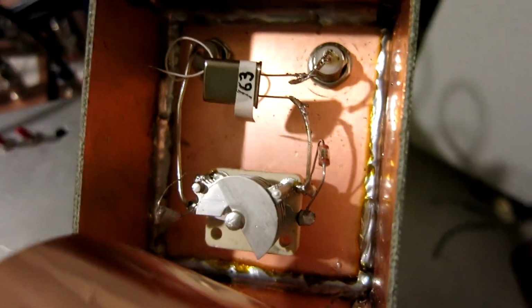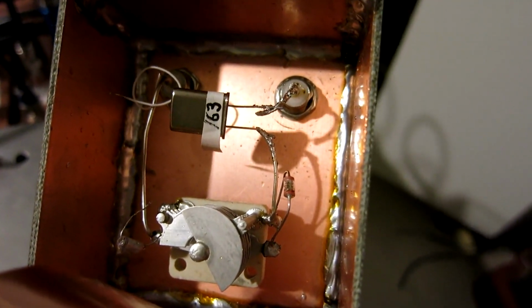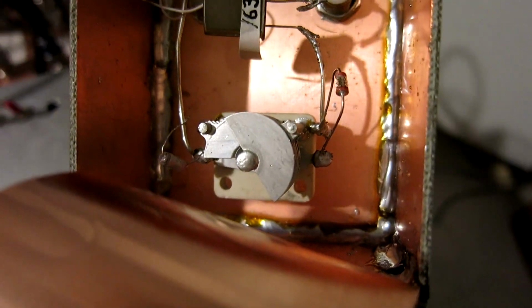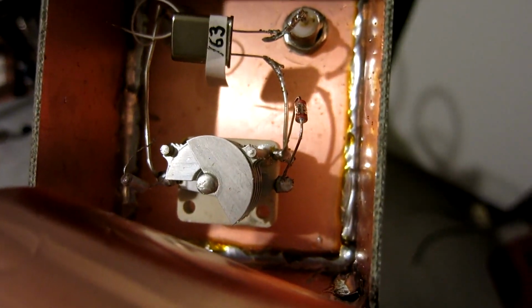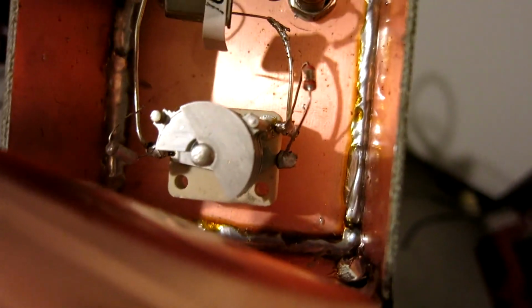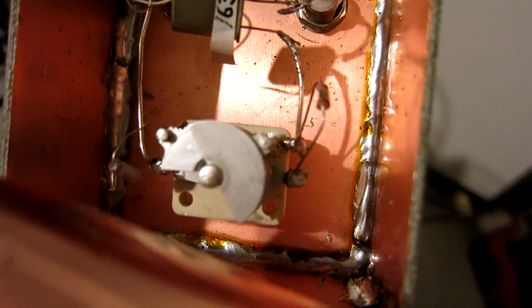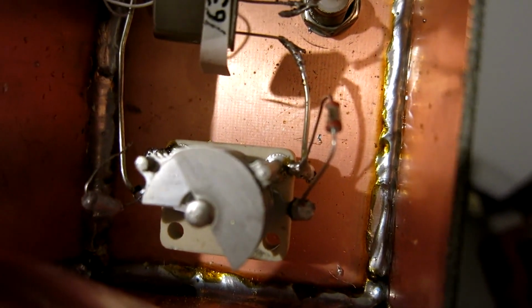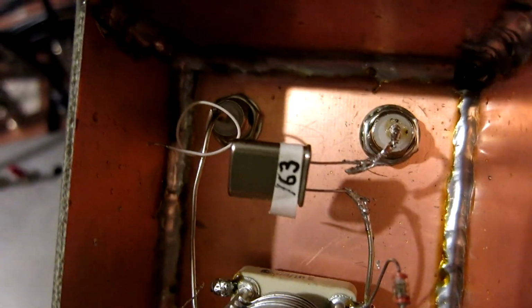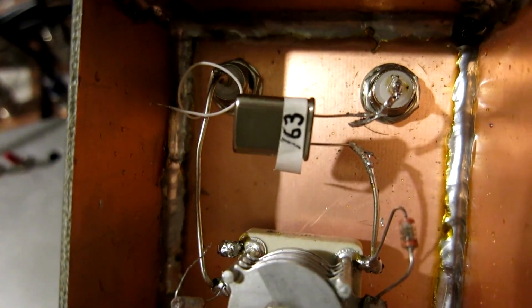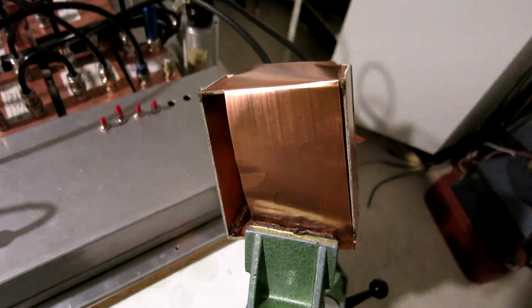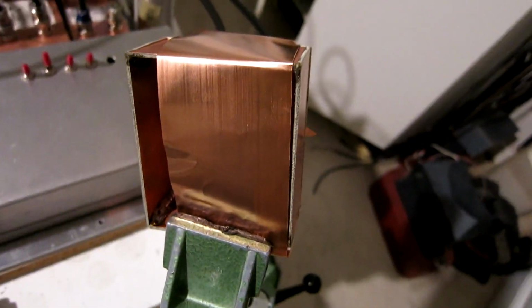Now I have crystal number 163 rather than the wire straight between the B and C connectors. There is a tunable capacitor in series and a small capacitor here in parallel with the tunable. And I have tuned it for a 0 phase shift. I can see in the interferometer that the phase is the same as the phase I had when this little white wire was across between the B and C connectors and with no crystal in here. And now it is well screened again.